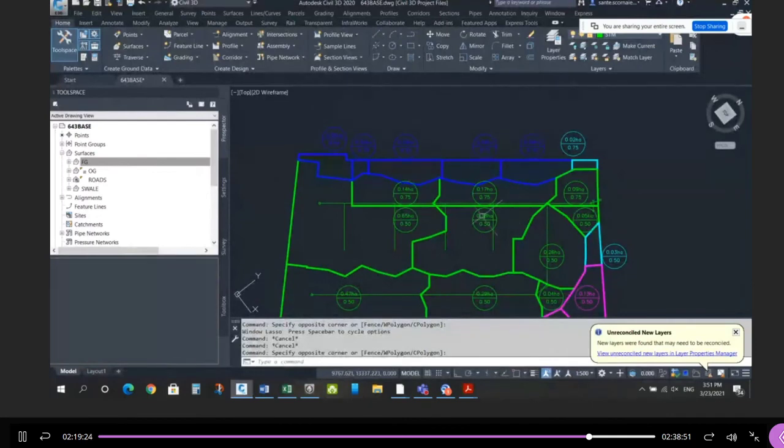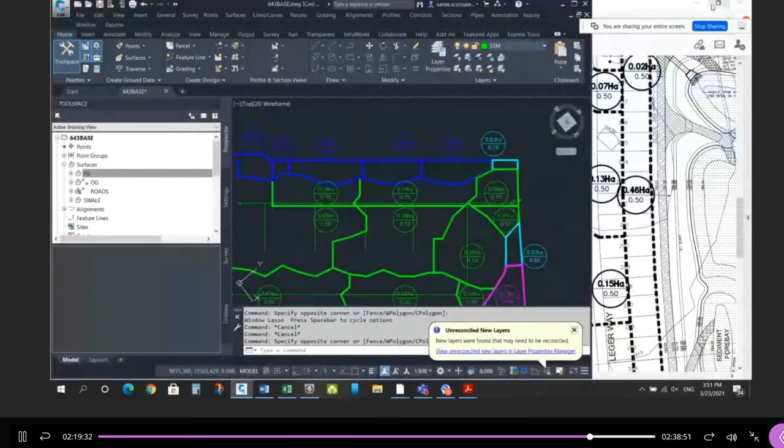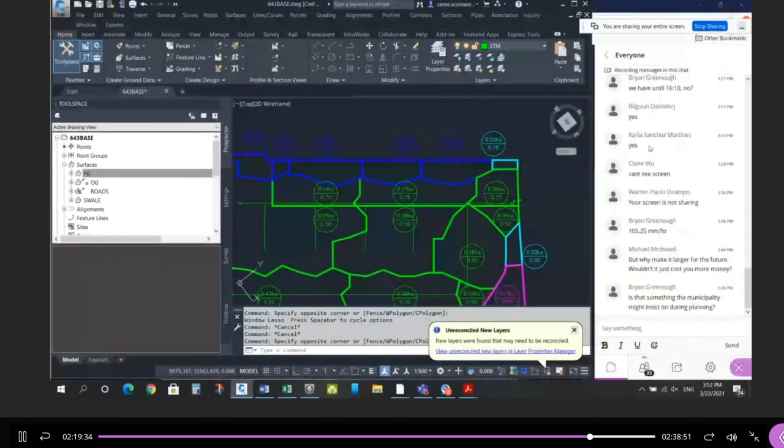I don't have to propose my own catch basins from the north coming down. All right. Any questions about that? It's a very theoretical calculation, but it proves the point. You can't just assume it's true. You have to prove it's true. Okay. You'd have to do the same thing here. These two areas are going to be tributary to the sewers on Ledger Way. So you'd have to increase those areas.